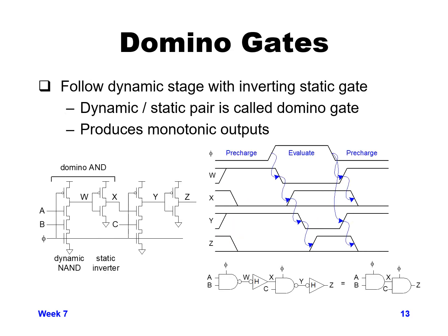So you might ask, if we could only have a single domino stage and we can't have multiple in series with each other, it might give us a little bit of timing improvement, but what good does that do us? But it turns out, while we can't have a domino stage directly driving another domino stage, as long as we follow each dynamic stage with an inverting static gate that can switch, it doesn't have a timing requirement on monotonicity,